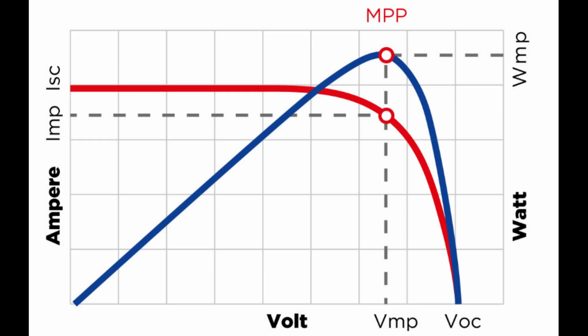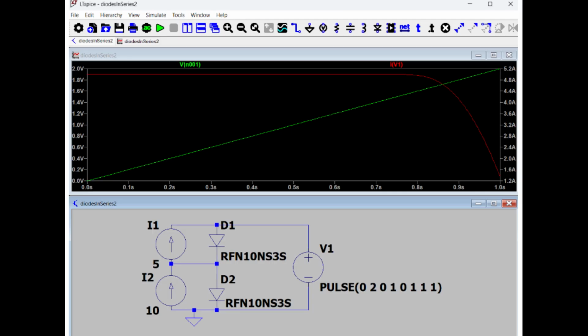A tracking circuit needs to track this peak point as conditions, such as lighting and temperature, change. If MPP is being tracked for a group of panels wired together, they all need to match with the same illumination. Otherwise, efficiency falls.